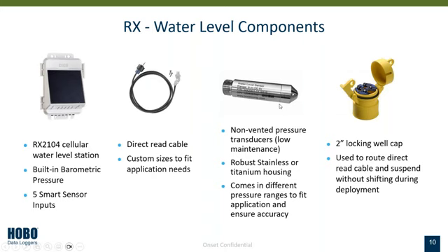So again, these are absolute pressure transducers. They're non-vented, so low maintenance, easy to use. It comes in either a robust stainless or titanium housing. And then we have all different pressure ranges to kind of handle your application. In most cases, the lower pressure ranges are good for some of these lake levels. But if you're doing some larger groundwater activity, we have them up to 250 foot of water depth.